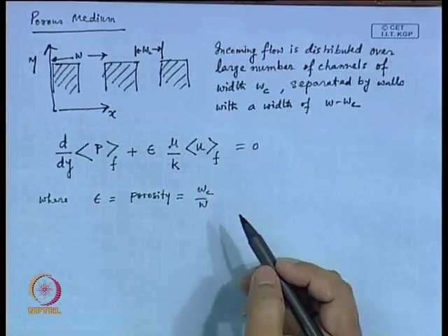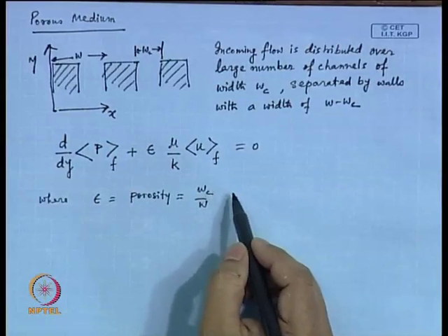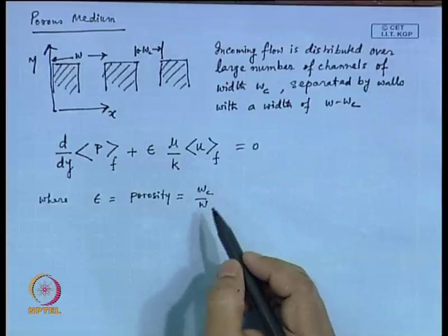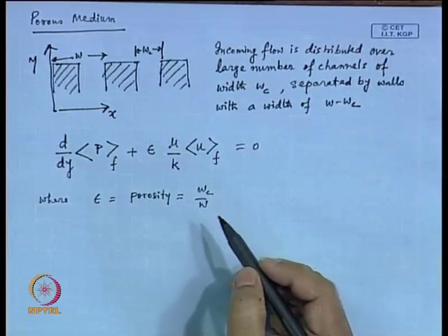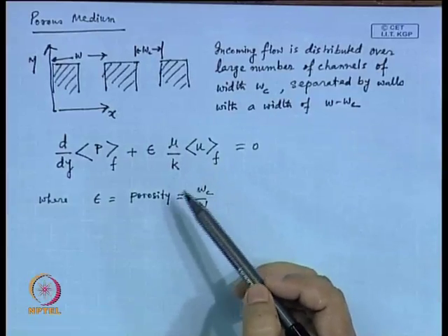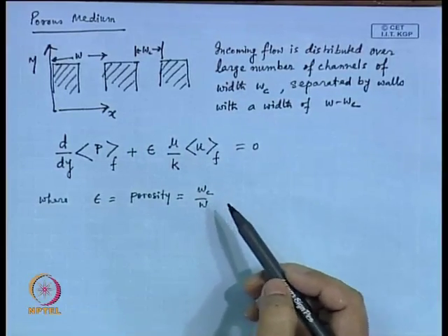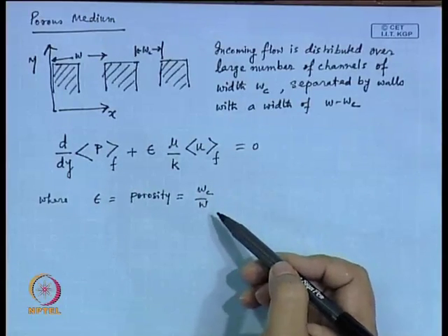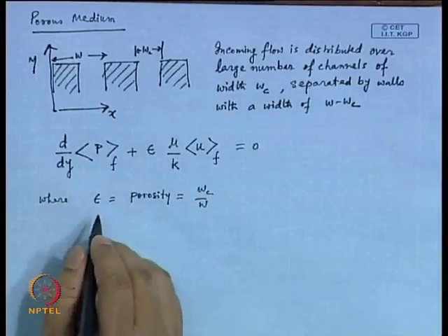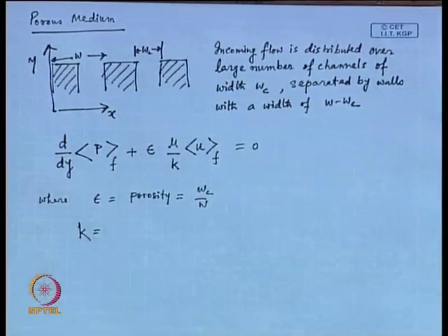Basically, you have another dimension added to it. Porosity is considered volume by volume, the volume of void divided by the total volume, right. Here you have only one dimension you are considering. So, the other two dimensions need to be multiplied to this. You are considering that these two dimensions would be multiplied in the numerator and denominator, and they just cancel out. And K, typically this is considered permeability for flow through a porous medium.